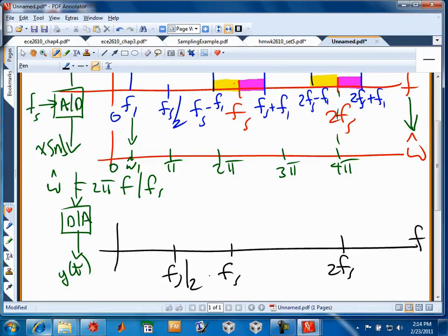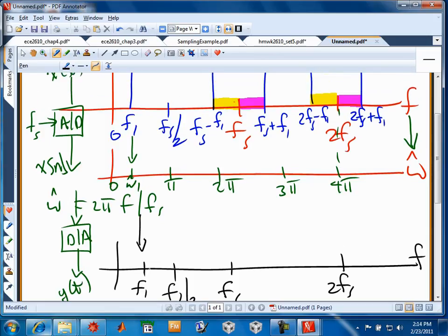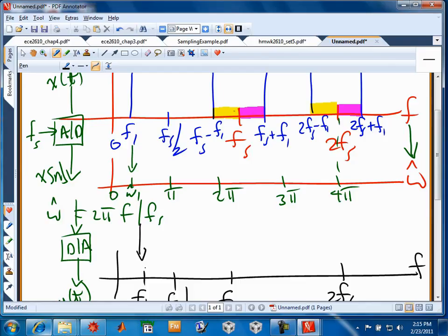So assuming that we have this box that can convert the samples back out into a continuous time signal, and that's something we haven't really explained yet, but we're getting there. Intuitively, though, where should the spectral line show up at the output of the D to A converter if things are consistent? It gets sampled at Fs. It was originally analog frequency F1. It becomes omega hat 1. So intuitively, shouldn't it come right back out here and sit back where it started? So it should be back at F1 again. And that's what the math talks about a little bit later in the notes and in the book.